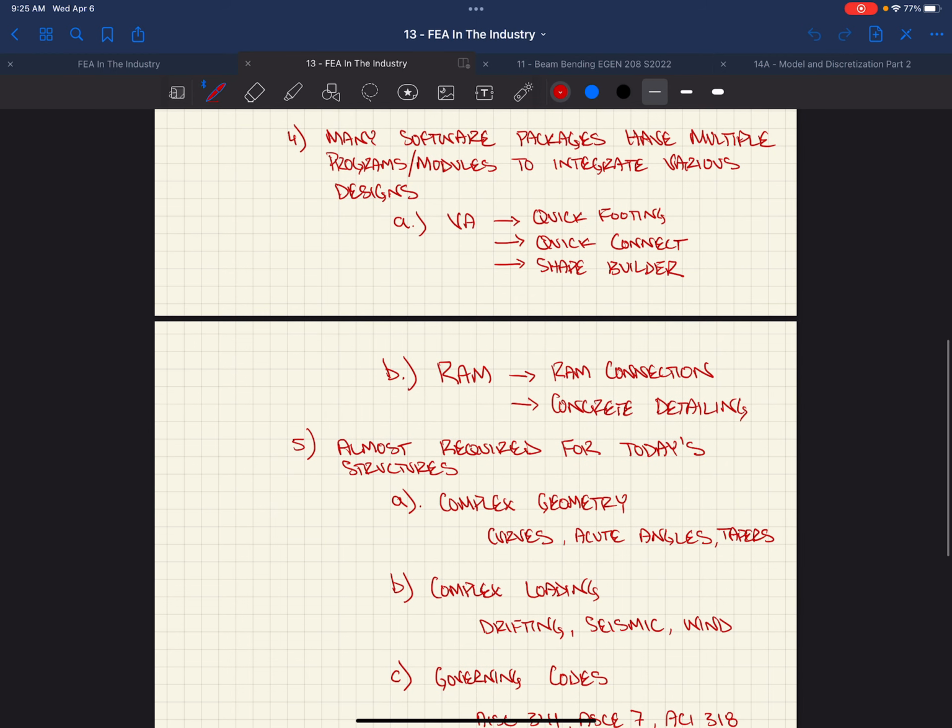It just becomes, you save money in construction even if you're going a lot more conservative, really conservative on your gravity. The steel fabricator doesn't have to order in like 60 different member sizes. They could go to the shelf for the common ones, right? 14 by 22s, 16 by 36s, stuff like that.